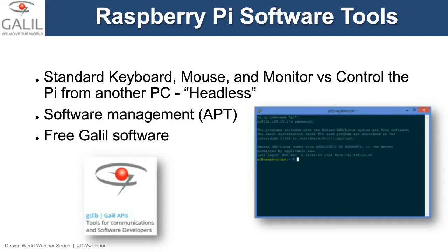You can get a program for Windows, and now you essentially open up a socket to the Raspberry Pi, and you can begin sending terminal commands to it and essentially control it remotely. So it even reduces the cost. You don't even really need a keyboard and mouse anymore. You just use your existing laptop or desktop, and it's nice. You can use that Ethernet connection as your main conduit of transferring data back and forth. You can use the file transfer protocol, pull files from it, push files to it.